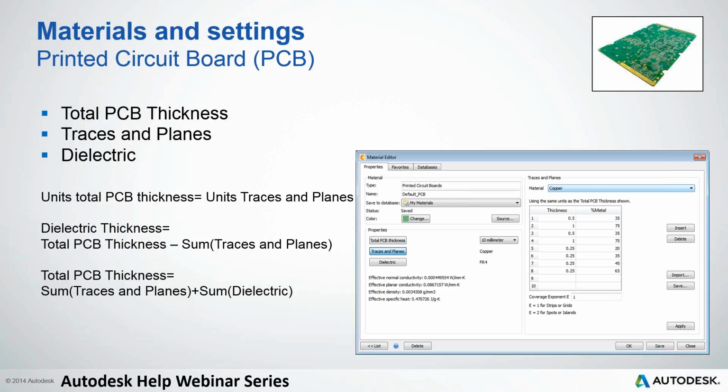Then when you go into traces and planes, you define a material for the traces. Generally, this is copper. It could be something else, I guess. And then you use this table on the right to define how many different layers of traces and planes there are, and what percent metal, percent volume is metal.